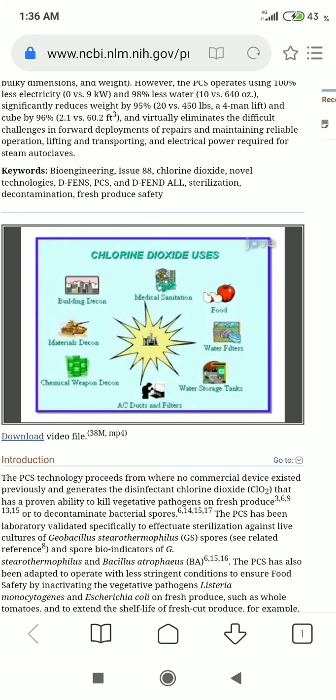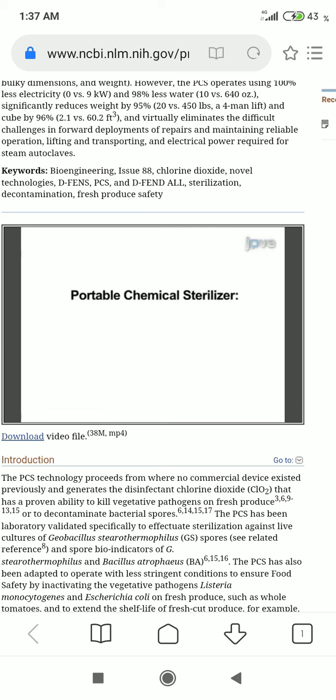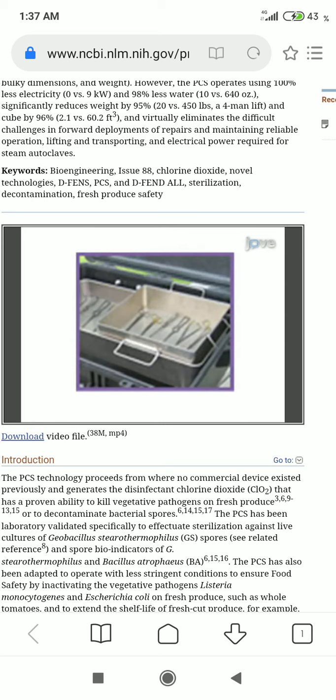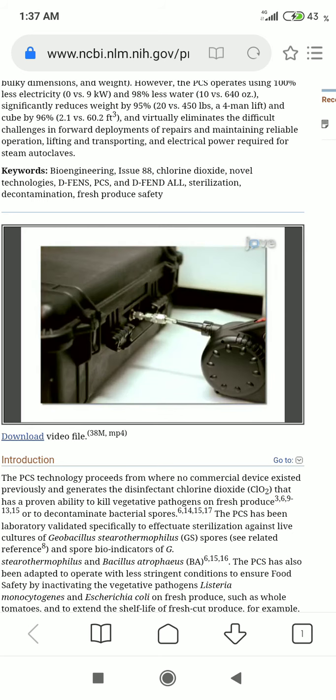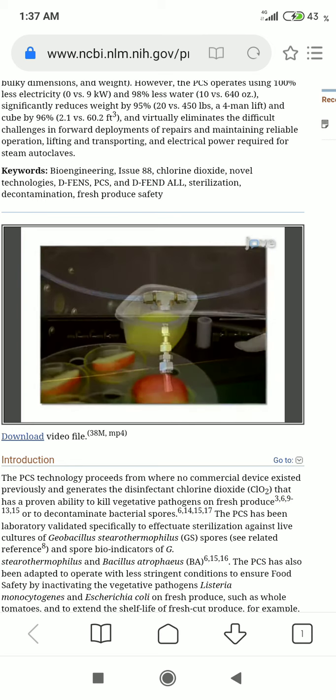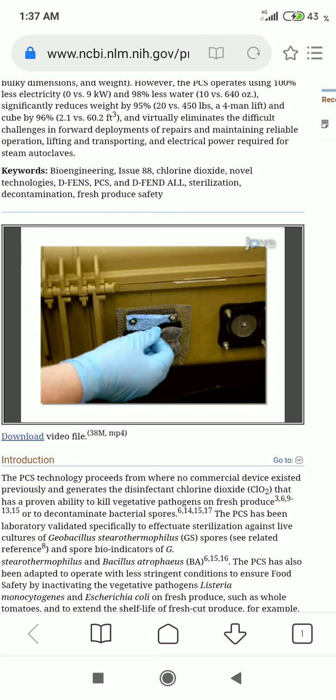This is achieved by adding a novel chemical effector to the chlorite-sulfite redox reaction at certain substoichiometric ratios to generate chlorine dioxide. The portable chemical sterilizer, a modern field autoclave, was invented by embellishing a rigid plastic suitcase with valves, an inlet valve connected to a circulating tube, a reactor vessel, and scrubbers to remove chemicals and protect users and